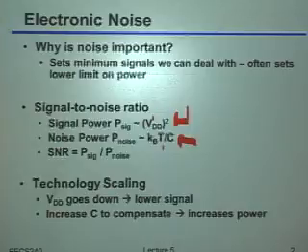So if somebody comes to you and says, I want my amplifier to have twice as much precision as before, or even 4 times as much precision, you should look at them and say, well, that's not really that easy, because that very quickly adds up. If they tell you they want 4x the precision, that's 16x the power if you're really limited by thermal noise.